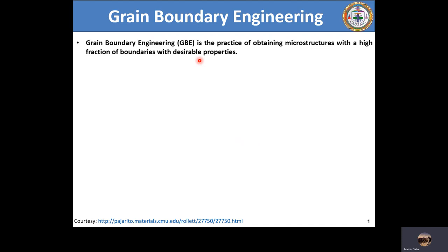And in the high angle regime, that is more than 15 degrees of misorientation, we do also have certain local minima, which we describe as the points of special high angle grain boundaries, or the low energy high angle grain boundaries in cubic materials. Those boundaries may also be termed as the CSL boundaries, or the coincident site lattice boundaries.